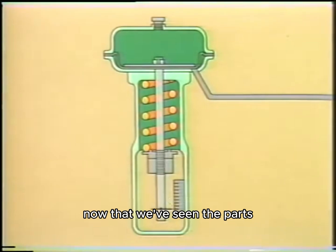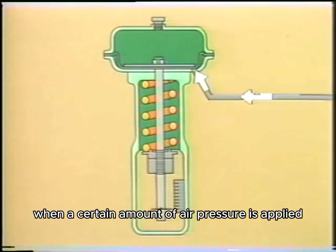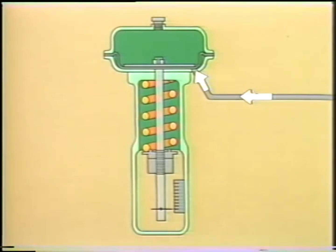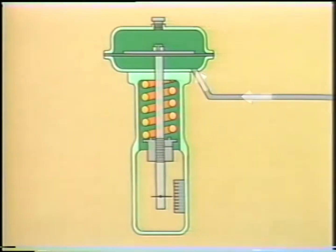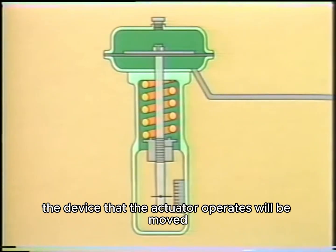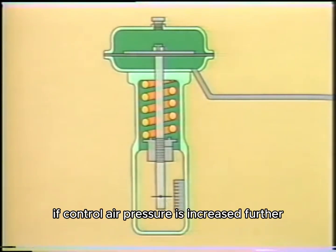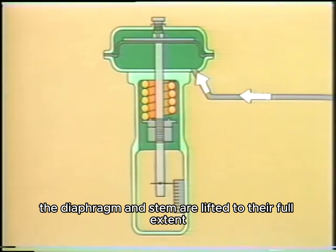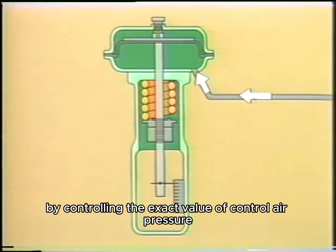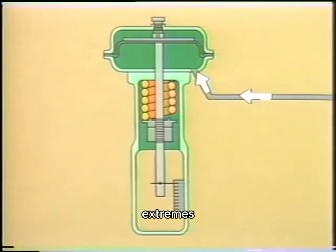Now that we've seen the parts, let's see how they function together. When a certain amount of air pressure is applied through the port, the diaphragm lifts, compressing the spring and raising the stem. The device that the actuator operates will be moved in proportion to the movement of the stem. If control air pressure is increased further, the diaphragm and stem are lifted to their full extent.